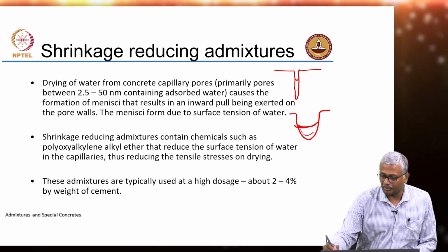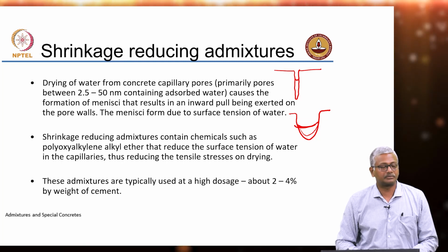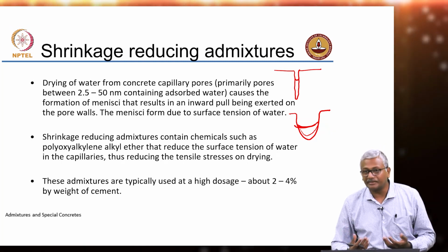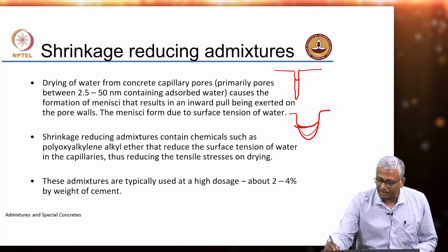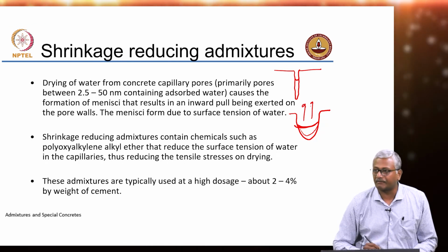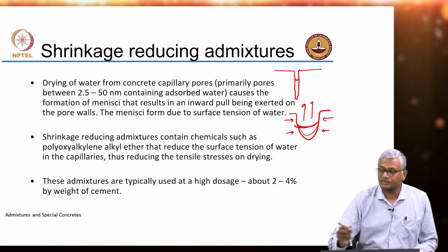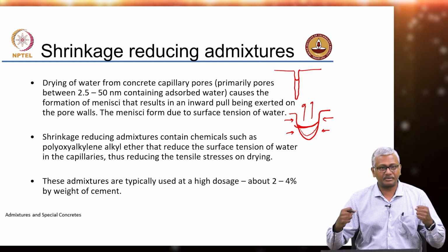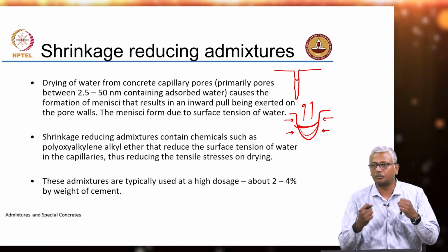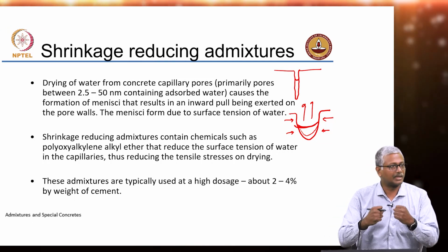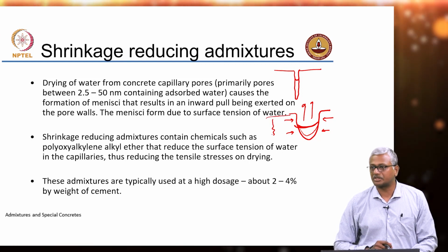This meniscus is going to get a lot more concave, and you are going to increase the angle of the meniscus, because drying is happening, leading to the water getting evaporated, and because of this there is pressure on the pore walls. There is going to be pressure on the pore walls, which is trying to put the walls in tension, or the concrete surrounding the pore is now getting put in tension. So, when tension happens, we are likely to get cracking in the concrete which is subjected to tension, right.